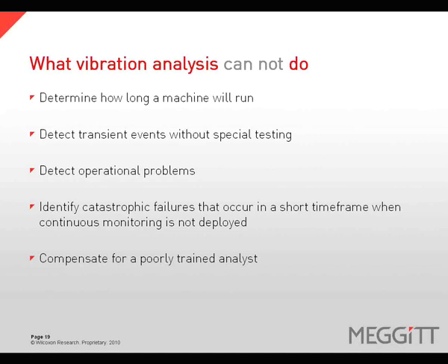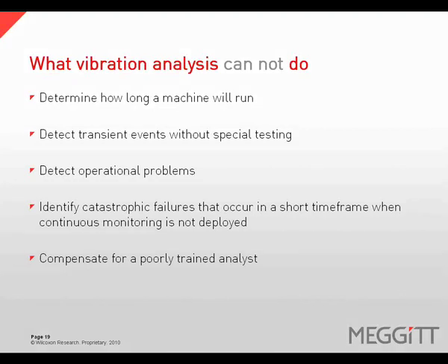Vibration analysis also cannot effectively detect operational problems, transient events without special testing, or catastrophic defects that fail very rapidly if continuous data is not collected. Likewise, vibration analysis can be unsuccessful if the user is not properly trained to collect the appropriate data and interpret the results correctly.